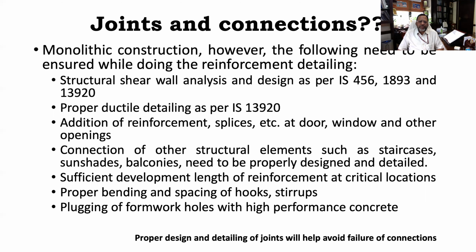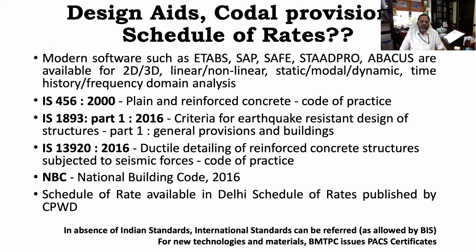Also, it's a formwork system, and you need to lay the services and all. After laying services, it is necessary to plug all the formwork holes with high performance concrete. Otherwise, they may become sources of water penetration at a later stage. And the most important thing for joints and connections is design and detailing as per the codal provisions to avoid failure of connections in the future.